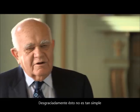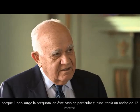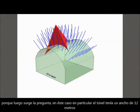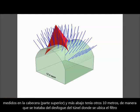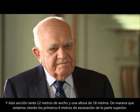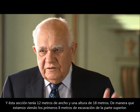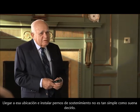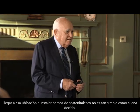Unfortunately, it's not quite that simple, because the question then arises, and this particular tunnel was 12 meters in span, taken as a top heading and then benched down another 10 meters. So it was the tail race tunnel of a hydro scheme, and 12 meters span, 18 meters high. So we're looking at the top heading, the first 8 meters of excavation. And to go in there and install rock bolts is not as simple as it sounds when you say it.